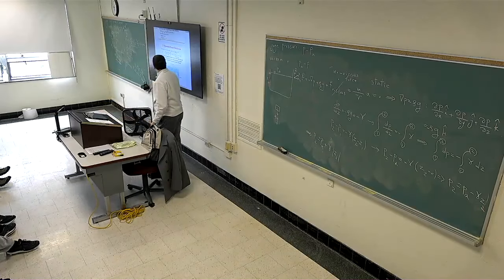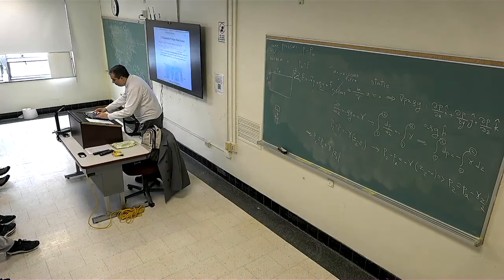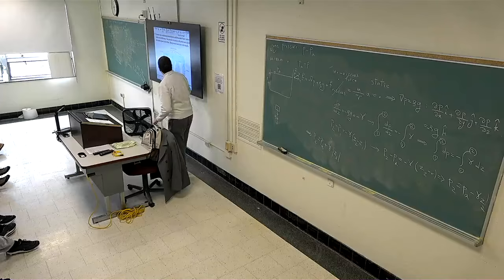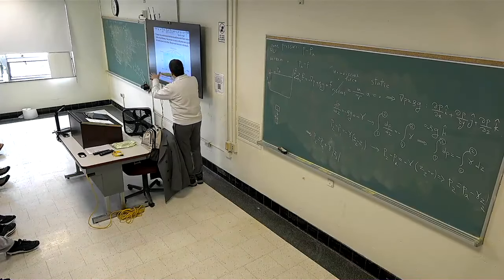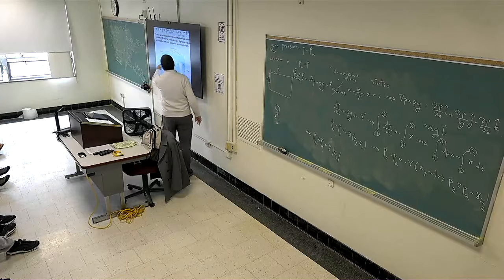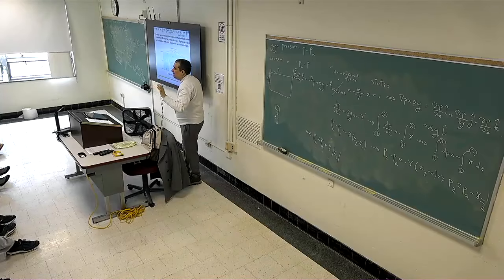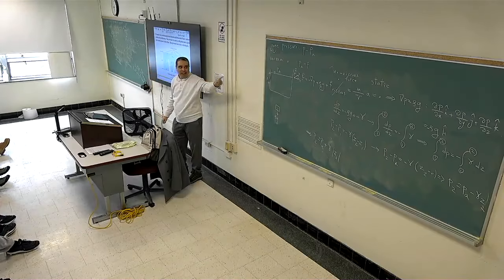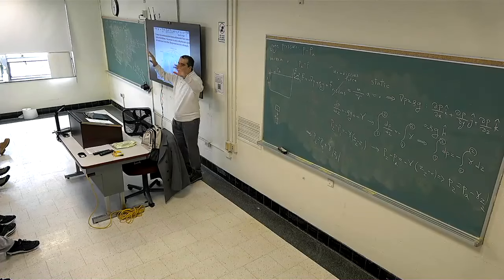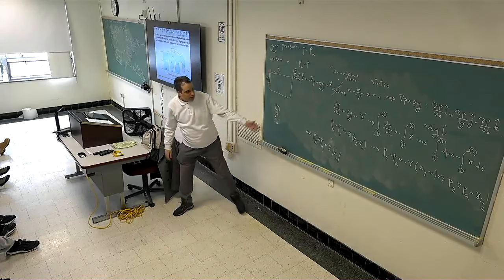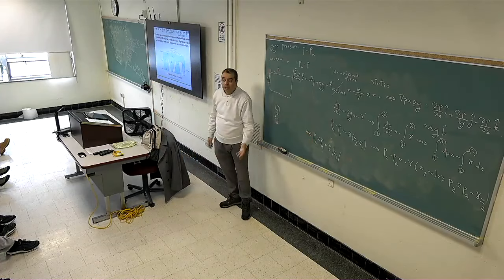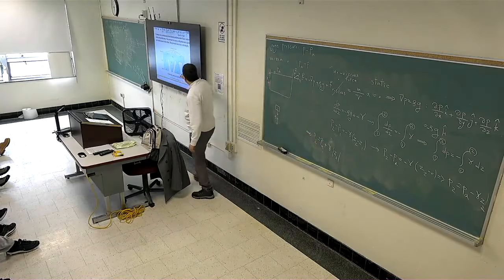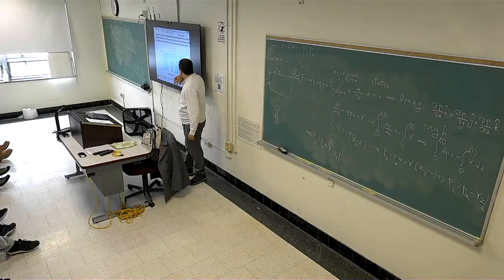Okay, let's consider this swimming pool, for example, or this dish of water, this bottle of water. Pressure at A, B, C, and D is the same. Why is the pressure the same? Tell me based on the equation I wrote at the end of this board. It's the same Z. Yeah, the Z is the same.